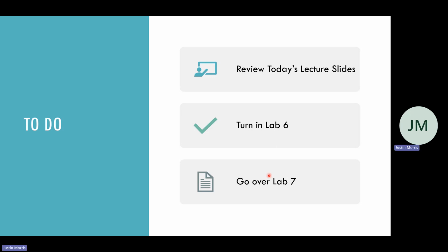Then your control is, again, you copy those states and you simplify the conditions to be single bits from the data path. Then you implement the control, and you don't have to do the whole finite state machine excitation table and everything. From that finite state machine diagram, you can just do behavioral logic.